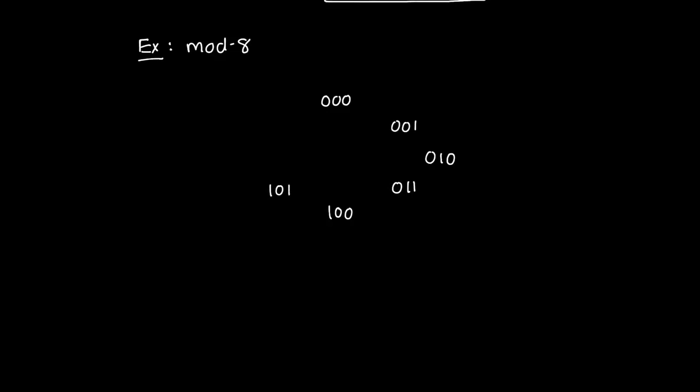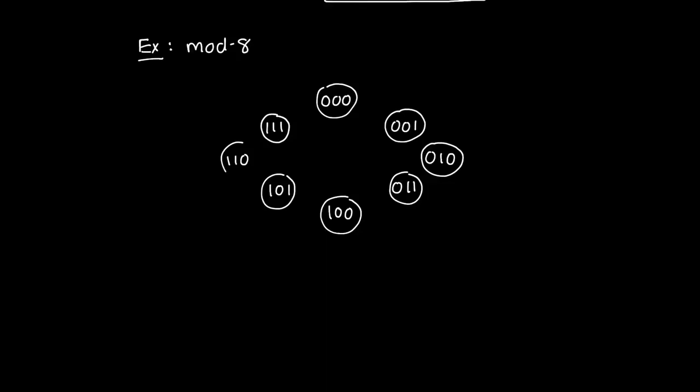And I'm going to draw the state transition diagram. Then I put bubbles around all my states. My states are simply my counter outputs. I'm going to do an up counter in this example, but it's exactly the same strategy as for a down counter, and we're going to see that. Again, that's unlike ripple counters, where I had to wire up my ripple counter differently depending on whether I was wiring an up counter or a down counter. But let's make it a standard mod 8 up counter, and let's see how it differs.